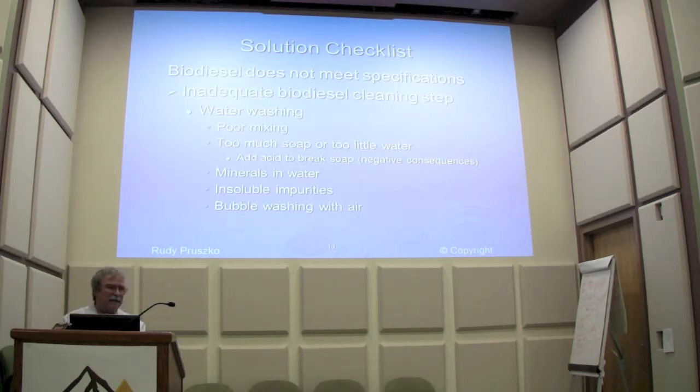It's mainly for the acid number. I mean, if you had beautiful conversion and you started out with a pretty good feedstock and you didn't have any water, because water creates free fatty acid, and everything went through great, and you added a little acid because you broke the soap, or you shouldn't have had soap if you had good feedstock, that little bit of acid would not be a problem as long as it's within spec.